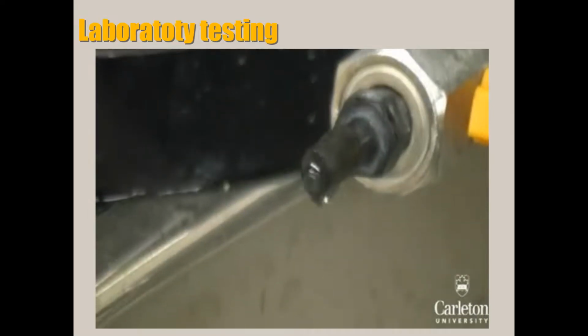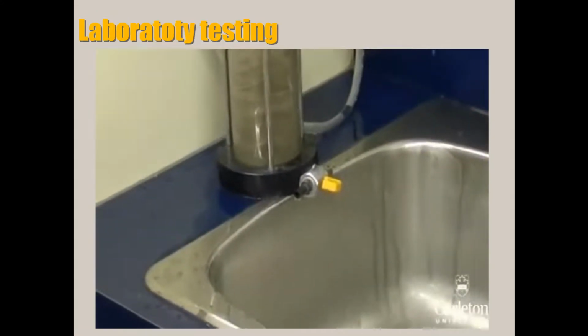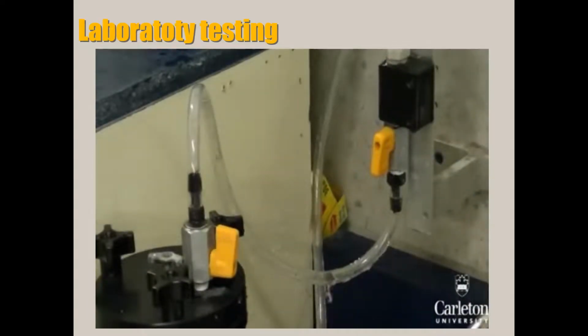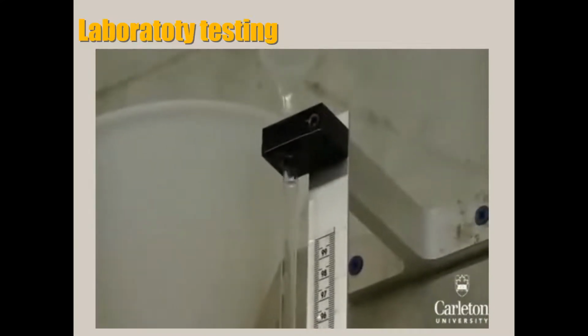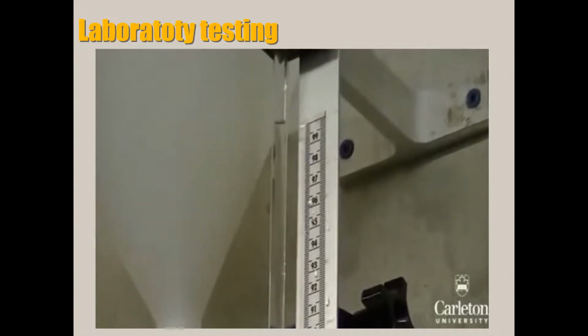If there are bubbles in the pipe, gradually add more water to the system so that the air can be flushed out. Close the valve at the top of the test cylinder so that the water level in the pipe remains constant. If there is water left in the funnel, open and close the valve so that the level of water in the pipe falls to a measurable level.